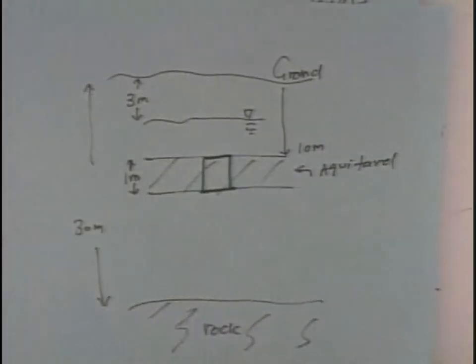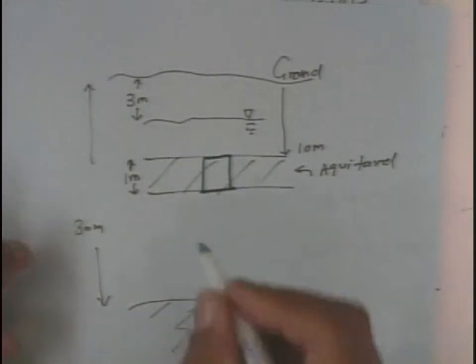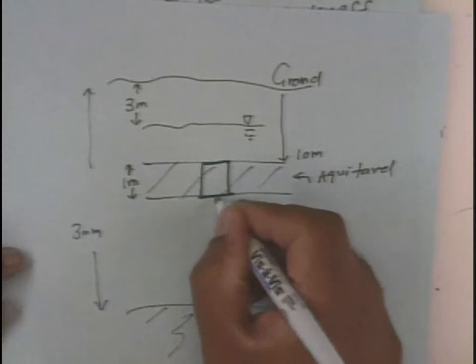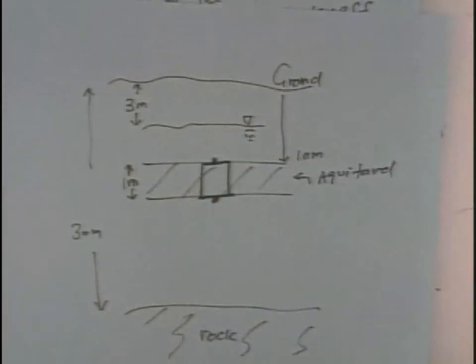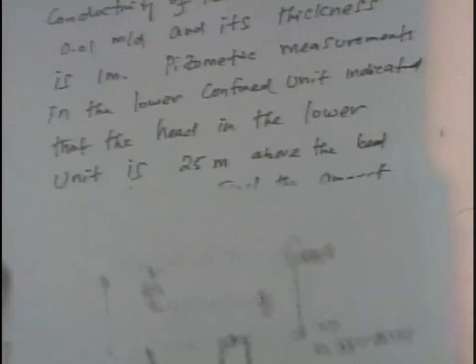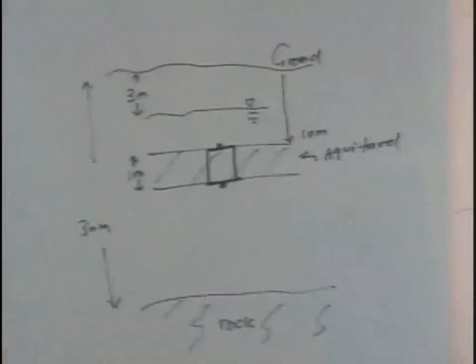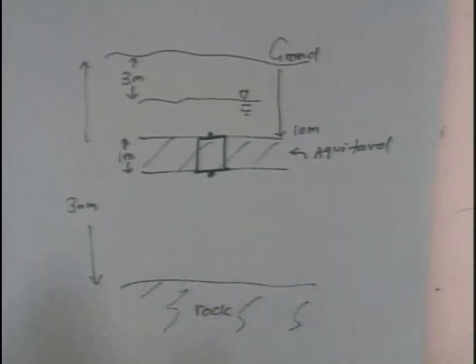Okay. If I'm a nice guy, I would have given you, well, there is a 1 meter soil column, there is an inlet pressure, there is outlet pressure, find the flow through the system. And the area of the soil column is what? I gave you 25 kilometers squared. Okay? So from a planar area point of view, you're talking about a regional flow, a flow over 25 square kilometers of aquifer.